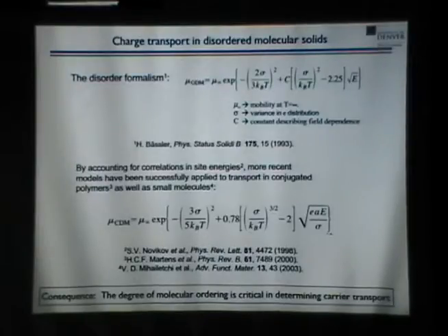So the bottom line is that the molecular ordering, both the orientation, the distance, and the relative energies between molecules, is critical in determining the velocity of the carriers through the film. So I should mention that these are all thermally stimulated processes. As you turn up the temperature, the hopping rate increases, and so the velocity also increases. This is the opposite of a conventional semiconductor like crystalline silicon, where you increase phonon scattering at higher temperature and mobility goes down.